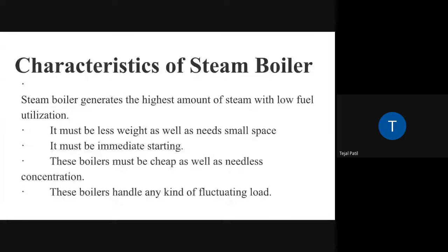As I said in the previous slide, in the fire tube boiler, you need to supply the treated water directly. Why? Because otherwise it will be very difficult to maintain, right? So that is one of the things by which you can reduce the maintenance.